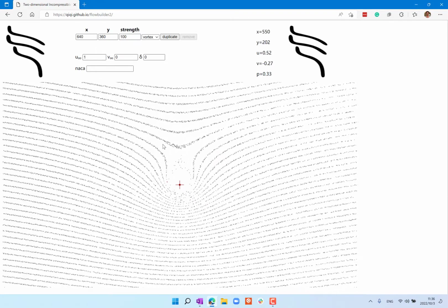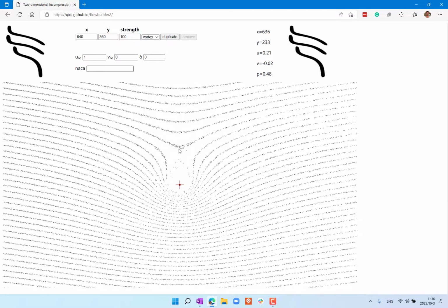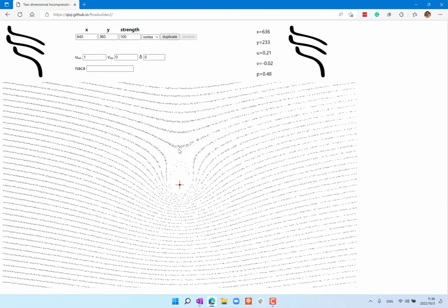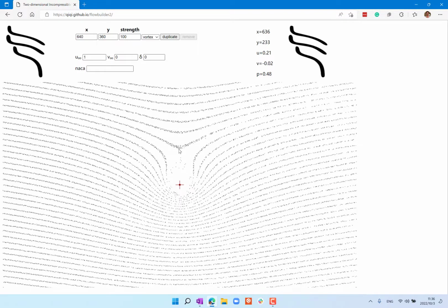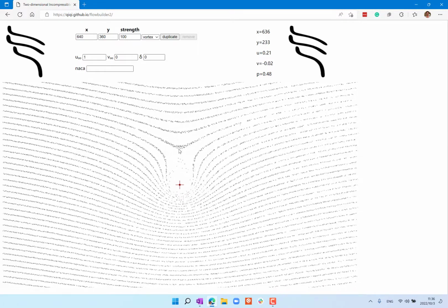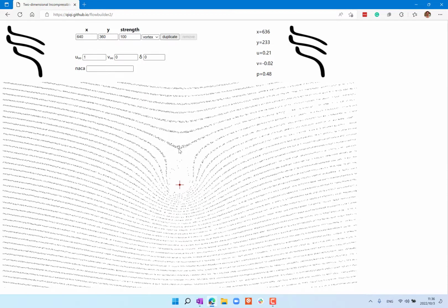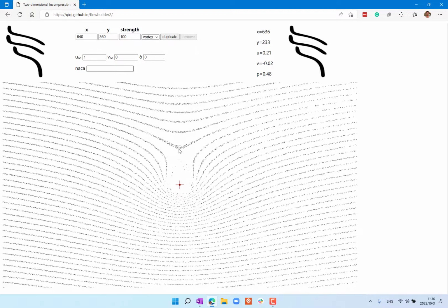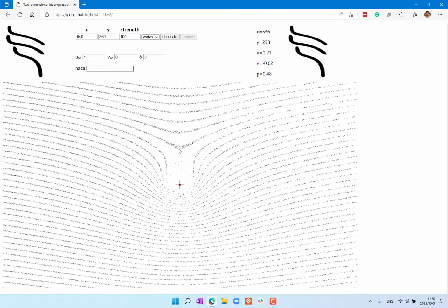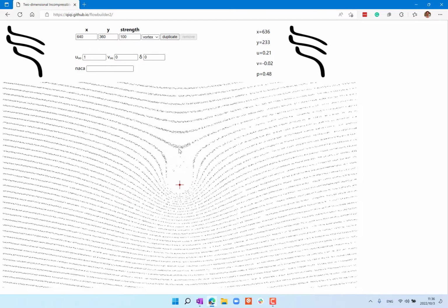The pressure is basically computed as the difference between the pressure here, which is minus half of u squared plus v squared, density is assumed to be 1, right, minus the pressure at free stream. So that's what this number is. That means pressure equal to 0.5 would be a stagnation pressure, right?